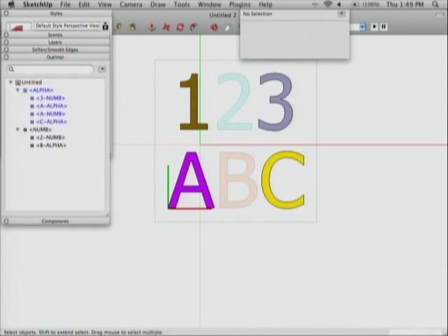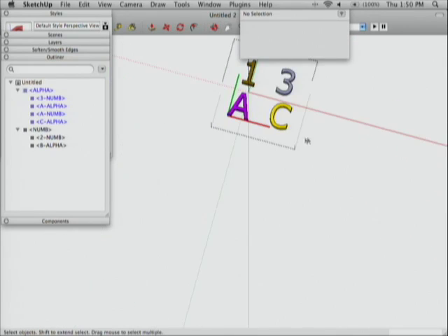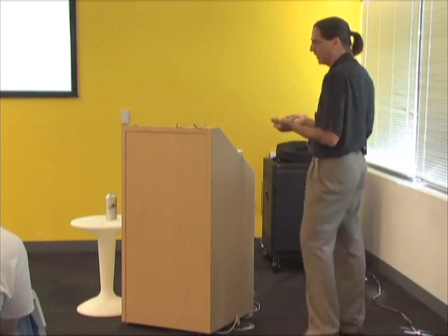And while I'm here, I want to talk about another little concept. When you're modeling and you go into a component, one of the really neat things about this is I can hide the rest of the geometry of the model. So I don't have to deal with it. And it's another way to hide geometry when you're trying to limit things. So sometimes when I'm working on models and I pick 4 or 5 things I want to work on, I'll just group them right there and then edit them and hide the rest of the model so I don't have to look at anything else, and all the other context goes away from around me. I create my own little universe locally. So I'm going to go back out.